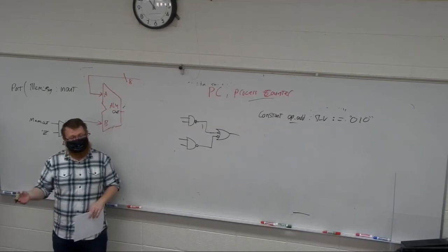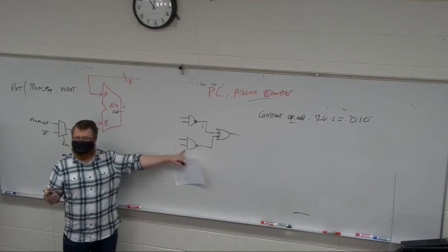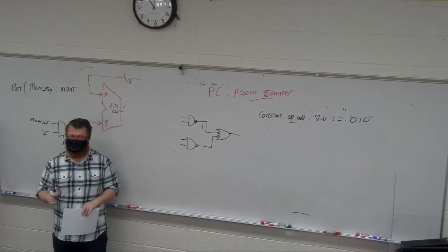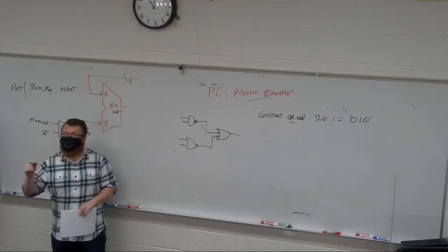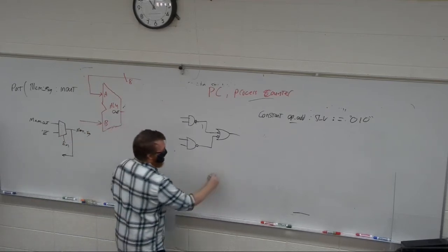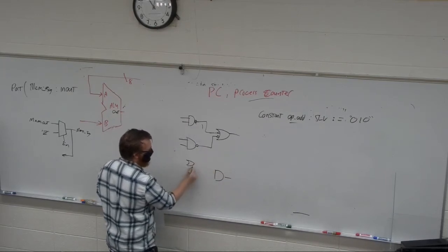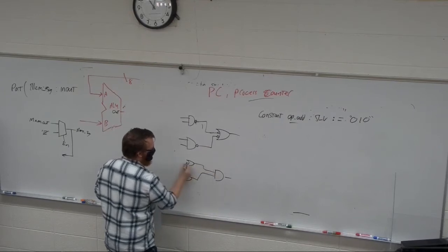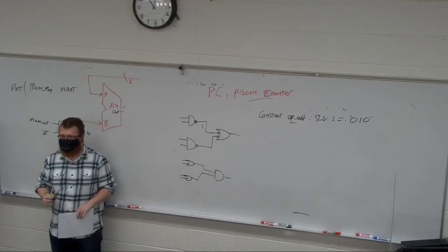If I were to ask you to create a circuit, so this is NAND, if I asked you to create a circuit using NOR gates, what would you do different? Use the max terms, right? Because with max terms, the output gate will be AND with OR inputs, right?